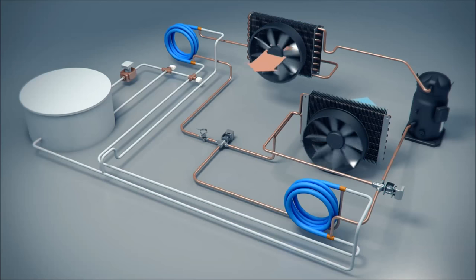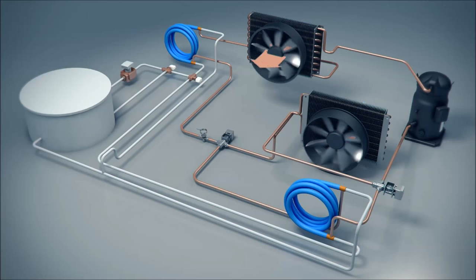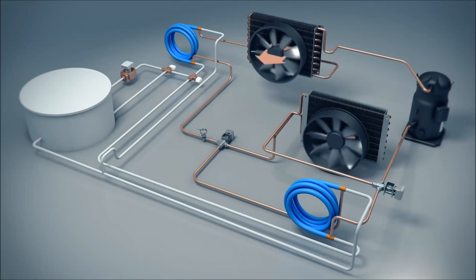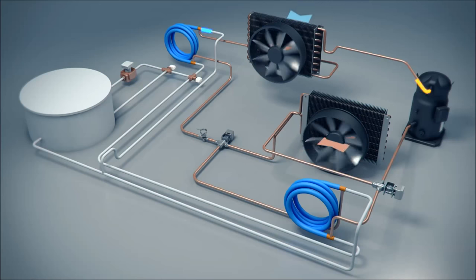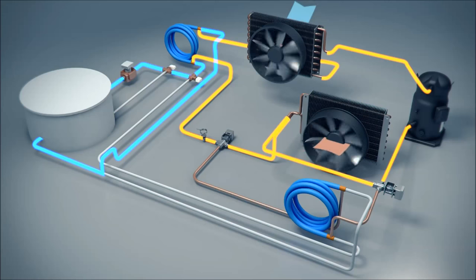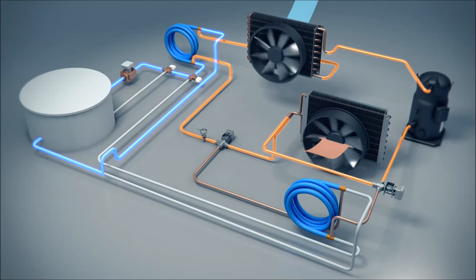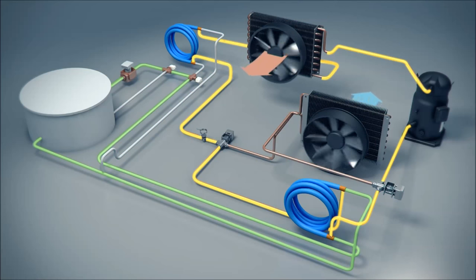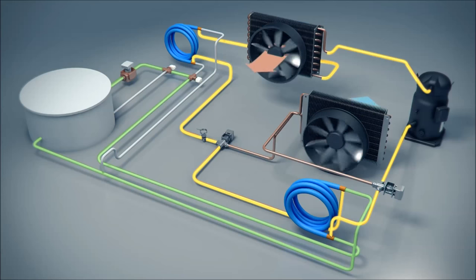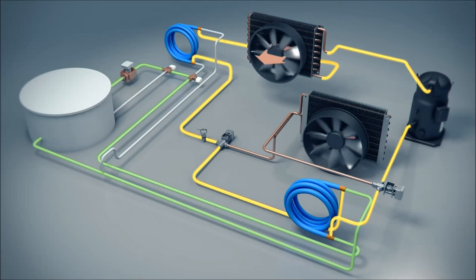The AC Companion consists of two independent refrigeration circuits in conjunction with two mutually exclusive hydronic loops. The primary stage AC Companion stabilization loop incorporates an AC Companion heat exchanger downstream of the condenser coil. The secondary stage AC Companion charging loop incorporates an AC Companion heat exchanger in substitution for the primary evaporator of the AC Companion stabilizing loop.